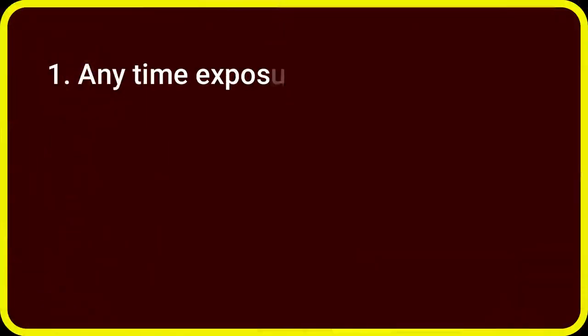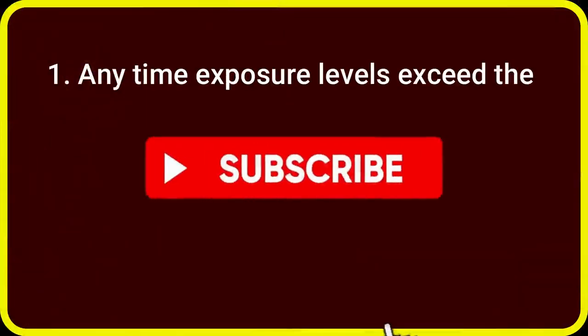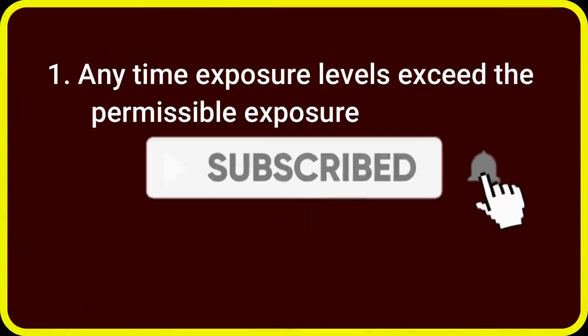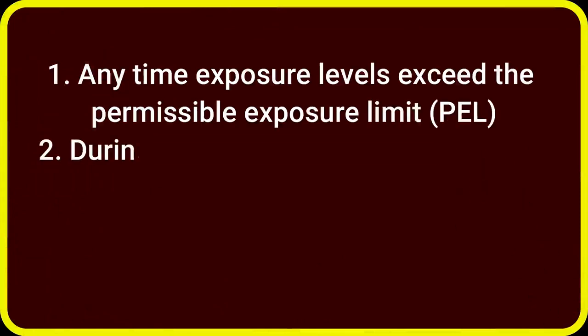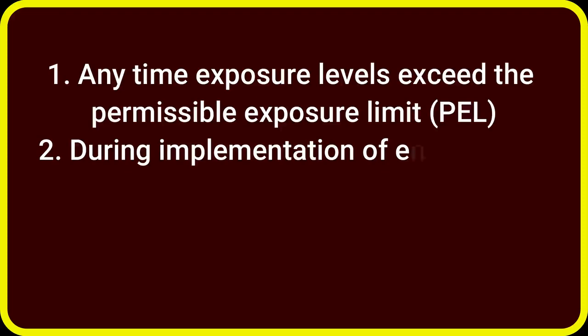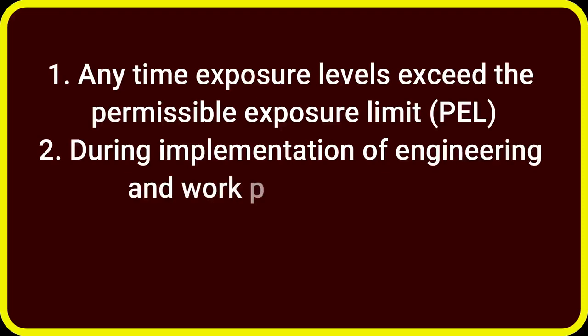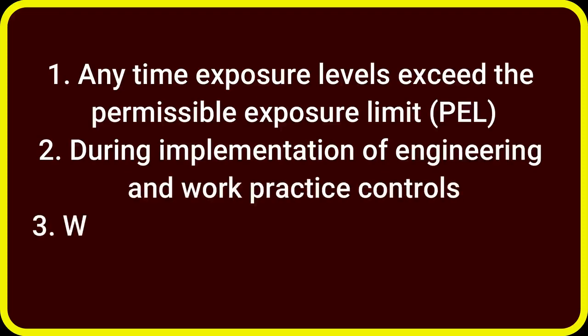When to wear respirators? Number 1, anytime exposure levels exceed the permissible exposure limit, PEL. Number 2, during implementation of engineering and work practice controls.